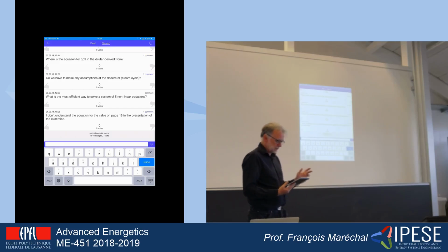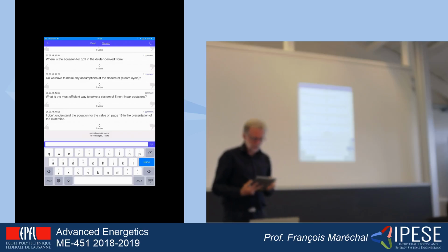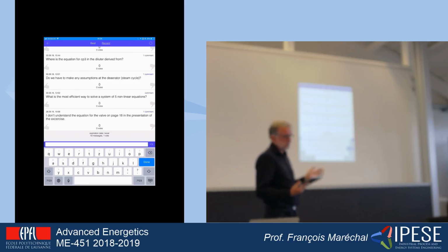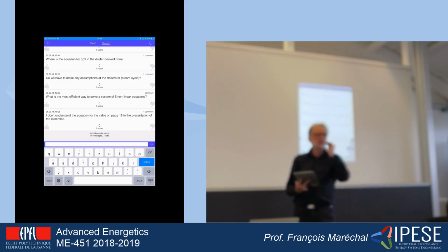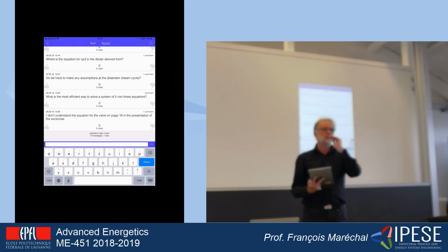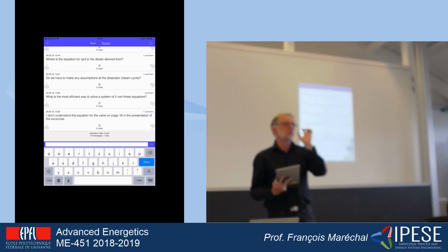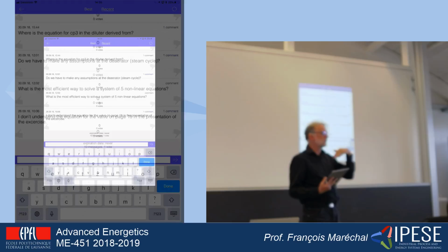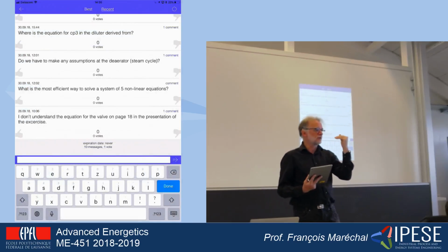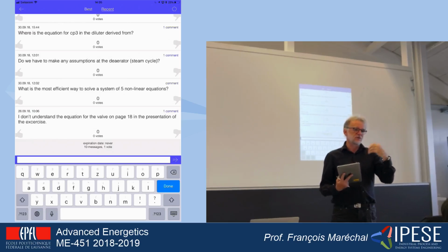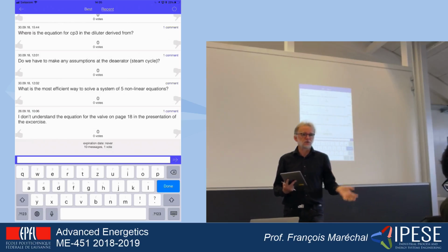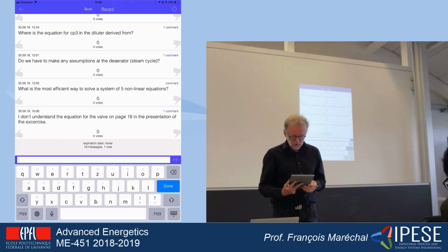So the question about the deaerator is already made, and of course the assumption is that the system is going to be reaching the ebullition. So it means that we have to give a set point of the liquid to be just at the pressure of the evaporation in the deaerator, so that you are sure that all the gases will leave the system.